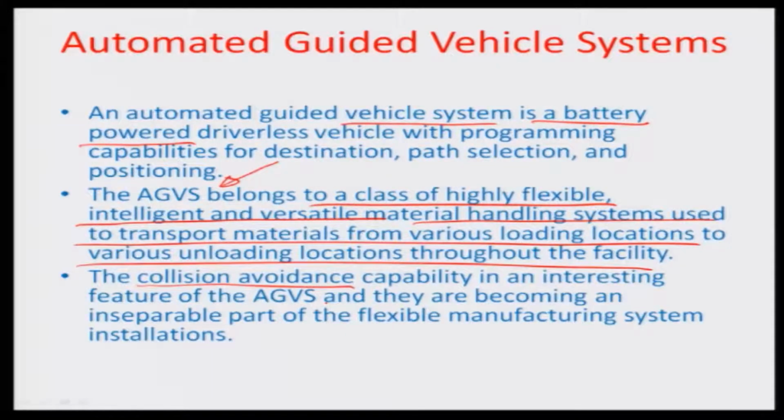Although it is not a complete robotic system, it is at least a partial robotic system which would have some intelligent capabilities like built-in sensors, and directives can be given to it through a path which can be laid out either as a fluorescent light path or paint path, or as some kind of electronic assistance by an underground cable, so that it can help to move the AGV in a particular direction from time to time.